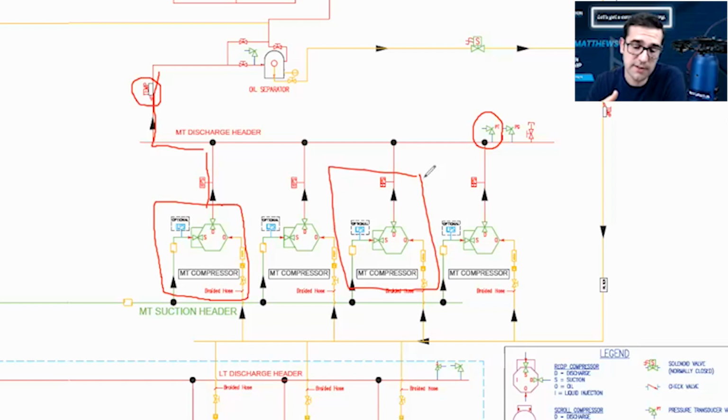But once again, I've talked to technicians and work with technicians that do work on hundreds of CO₂ stores, and they don't use gauges at all because they use a controller. They can read that information, and that helps them, because they can get into the controller and take a look at all the pressure transducers. And if one is reading way off, they can compare it to maybe 3 or 4 other ones and get a good idea if there's one running wrong. That's when they can get the transcritical gauge out and go match it up and get an idea. Is this pressure transducer way off, or is the wiring an issue? What's going on? Is there dirt in it? So they can check that stuff out.